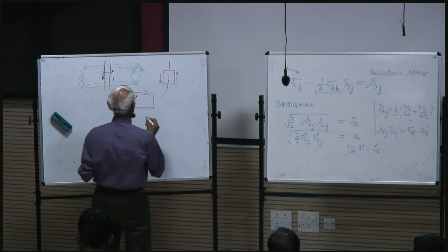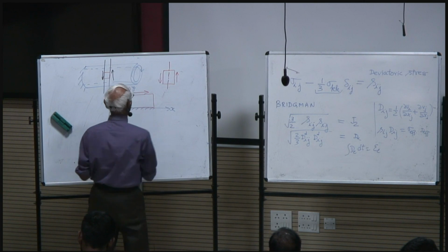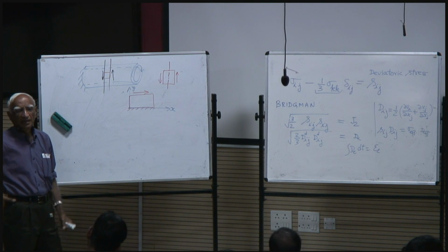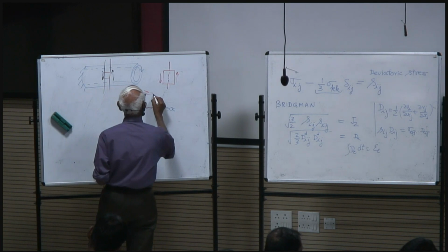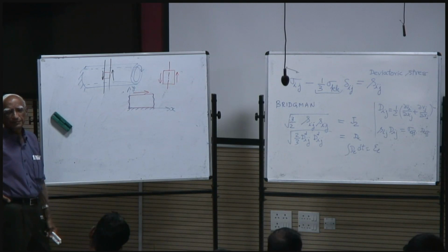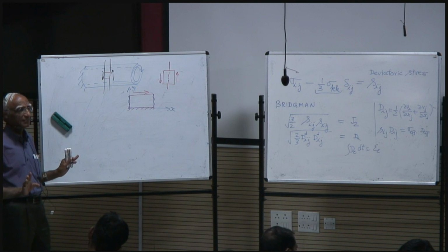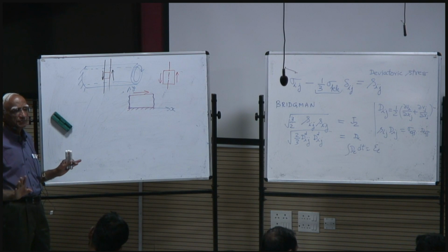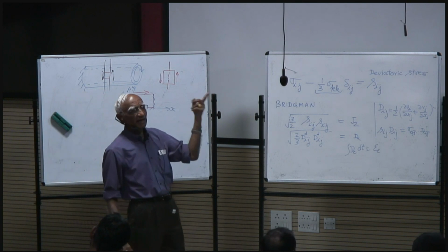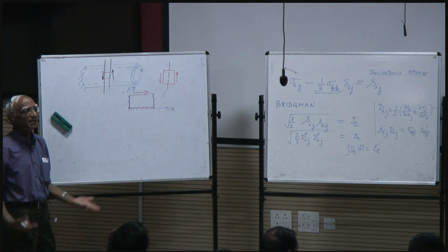So now let's choose the coordinate axis. So we have x-axis this way, y that way, and basically what I have is a simple shear problem. And these ends, you can say, they go forever. Things vary only in the y direction. So it's a one-dimensional problem. And there's only one component of stress, this S, called tau. And I wrote there tau. So shear stress.